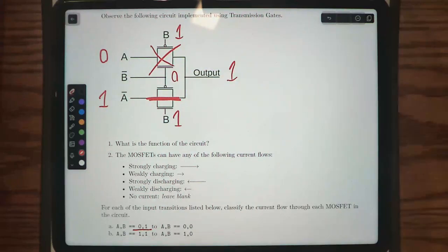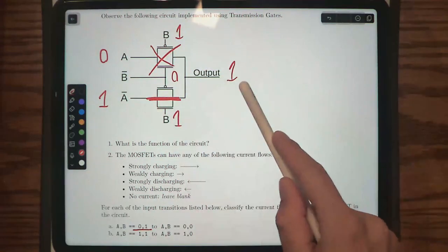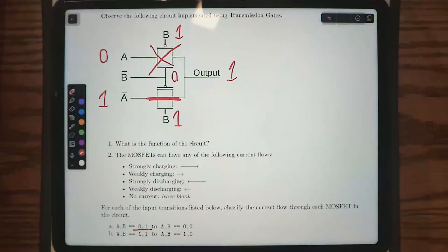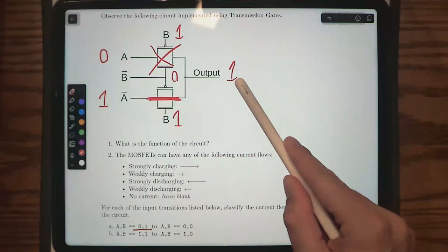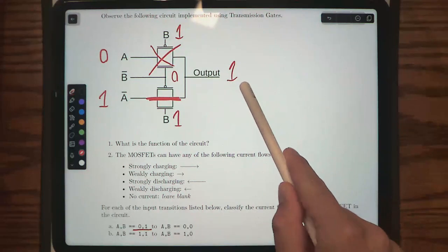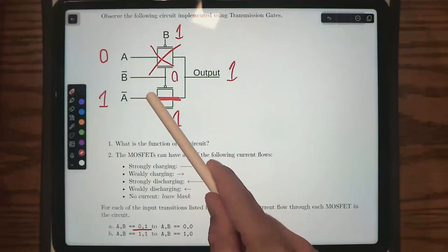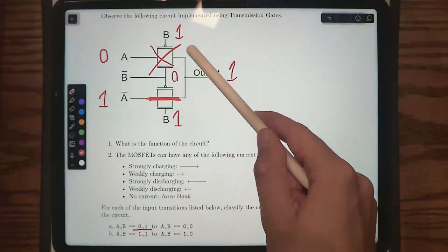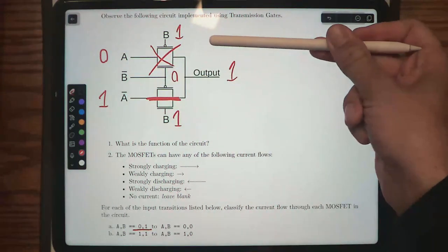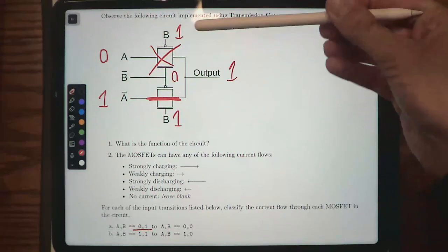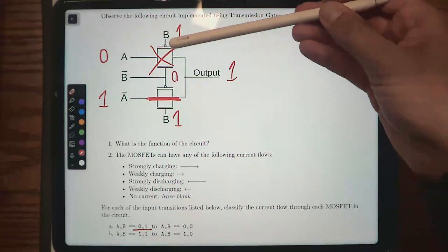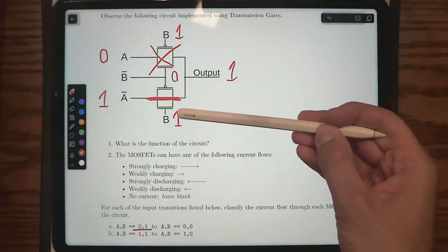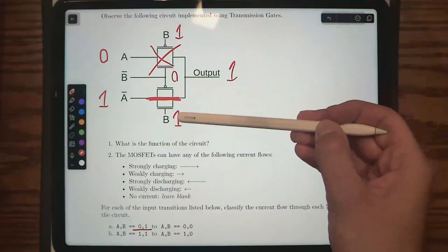Okay, cool. So this is going to be 1 volt. Let's assume that this is now at 1 volt. What is the current through these two MOSFETs right here? Yeah, the current through these is going to be 0. One way that you can tell is because they're disabled, right? But now if you look at these MOSFETs, these are enabled. So what will the current through these MOSFETs be in steady state?